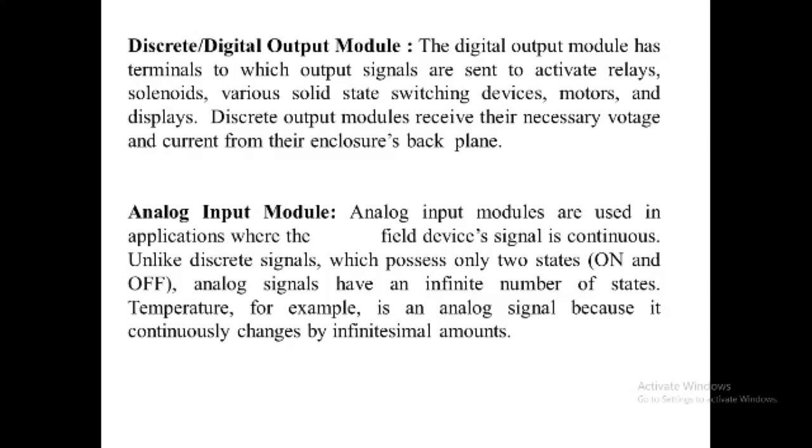Basically, to prevent these conditions, a power transistor is usually protected by a freewheeling diode placed across the load, that is the field output devices. Therefore, the DC output may also incorporate a fuse to protect the transistor during moderate overload. These fuses are capable of opening or breaking continuity quickly, before the excessive heat due to overcurrent occurs.